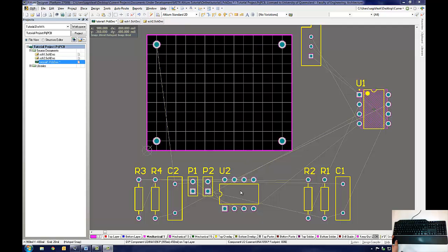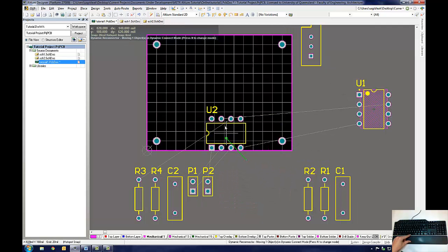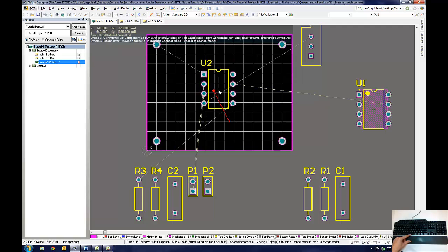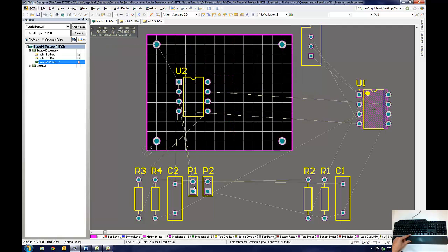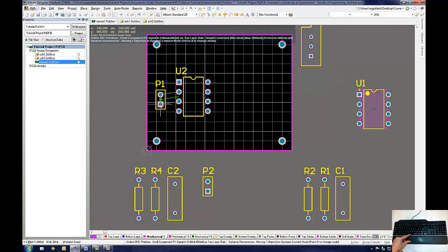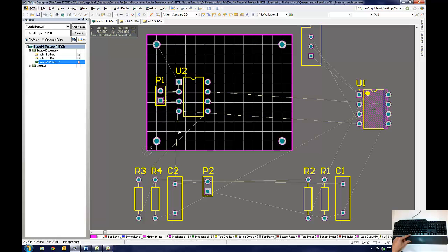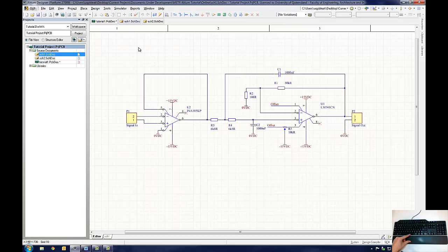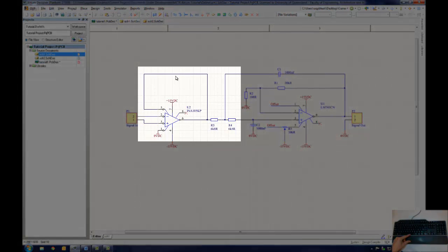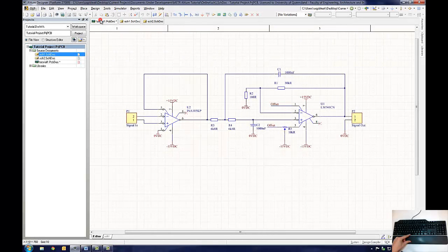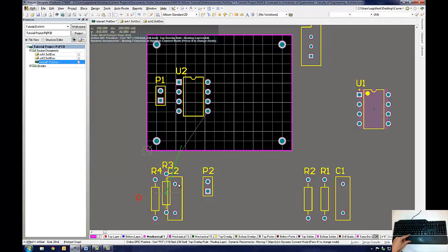There are many different techniques for laying out a PCB. One commonly used method is to place the components in a similar fashion to the layout of the schematic and piece the component sections together in a way which reduces the track lengths as much as possible. Altium already knows which points are to be connected together and indicates this with a thin, straight grey line. This line will indicate the shortest distance between 2 points, ignoring component bodies and other tracks.